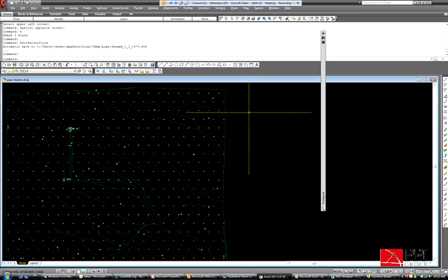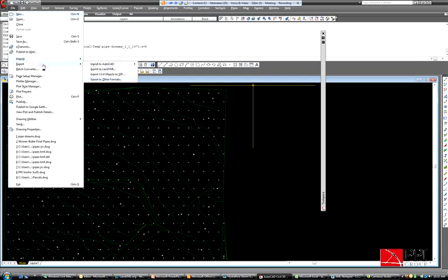You can pull those out through an XML into various hydrology programs if you want. A good tool is that the HEC programs will read an SDF, and you can do file, export civil objects to SDF, and now that it's in there as a parcel, you can get those watersheds out into HEC-RAS or other HEC programs. I know a lot of programs other than the HEC programs do read those as well. That's just one that I was looking at.